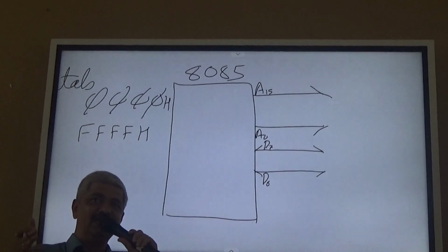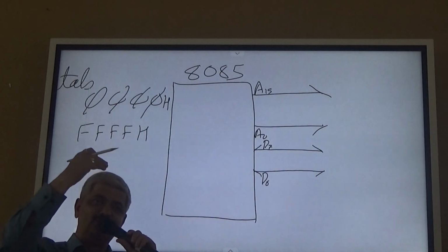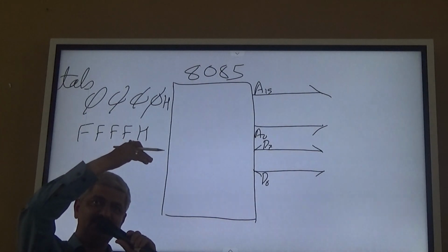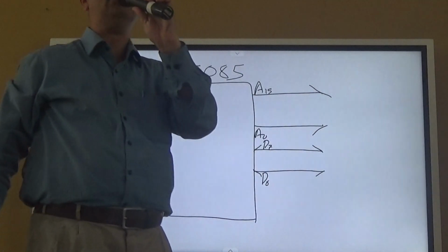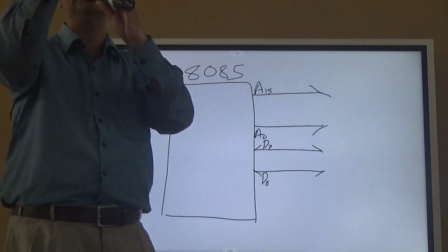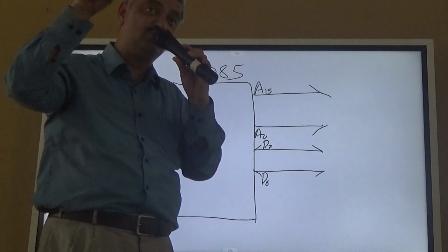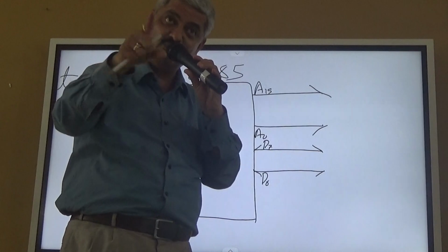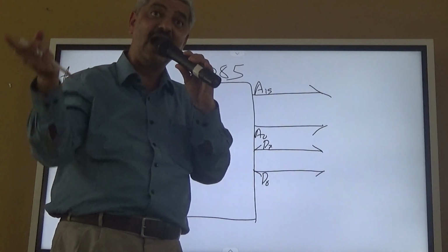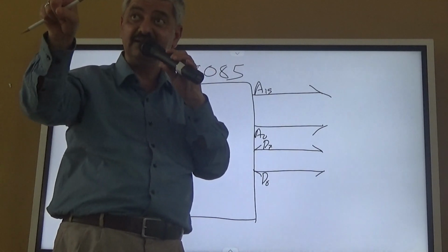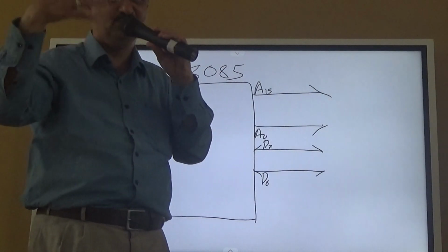The microprocessor's output lines are 16, its bidirectional lines are 8 data lines, and there are 2 more lines which indicate what operation it intends to carry out. Who decides which operation is to be carried out? The microprocessor, whether to read or to write, therefore both lines are output lines. To be precise, read bar and write bar, active low logic.